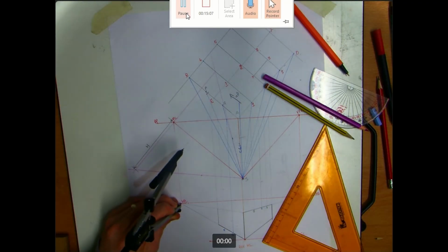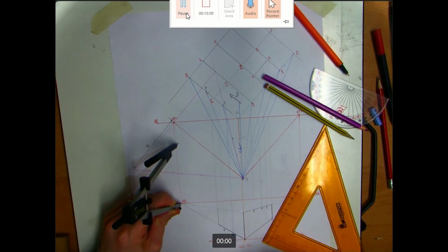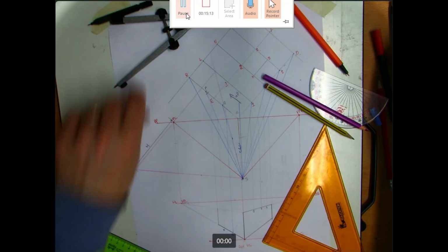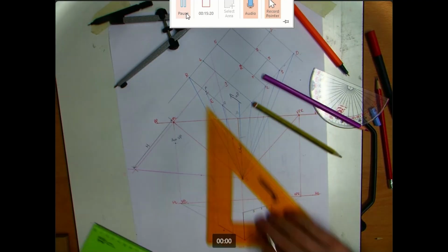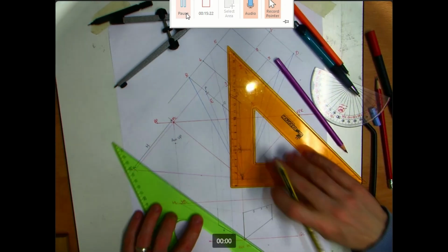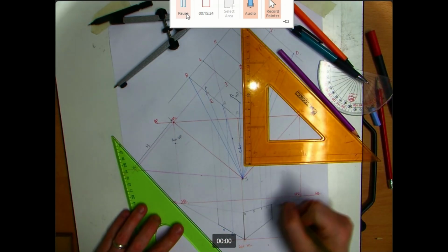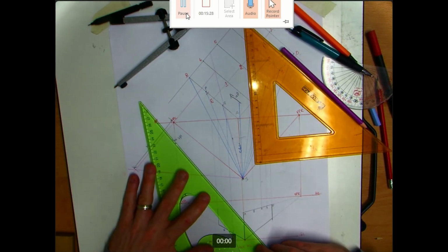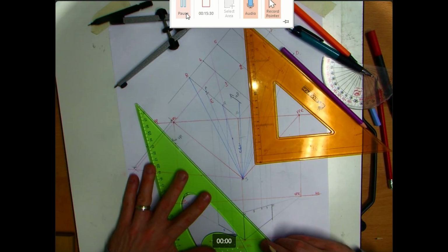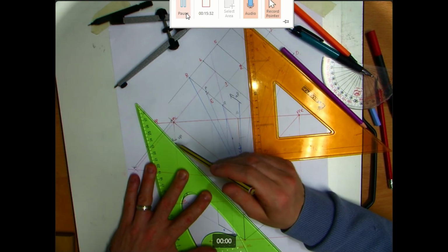And we apply it above the vanishing point line on the left, the VPL, to create our auxiliary vanishing point. So this point here is what we call our auxiliary vanishing point. That is the vanishing point for the slope. So at the top of A, at the top of D, we can bring these 2 points, and 1, 2, and 3, we can bring them all to the auxiliary vanishing point.